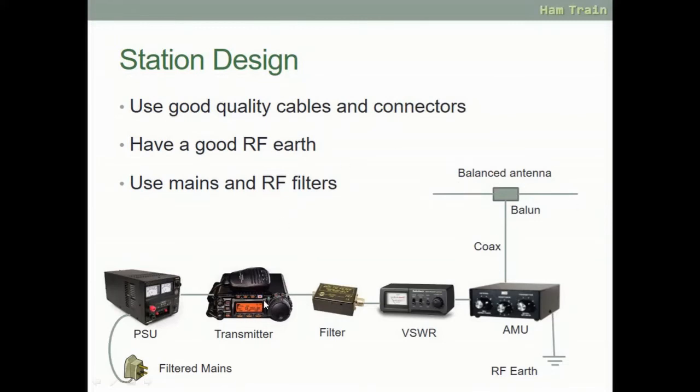There are some rigs, some transceivers, that have antenna matching units in. Most transceivers will also have an earth on the back of them as well, and nearly all antenna matching units will also have an earth socket on the back. Very often it's just a little screw that you put your cable round and bolt into place.